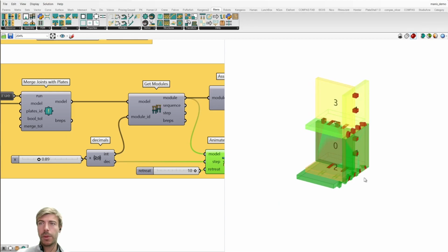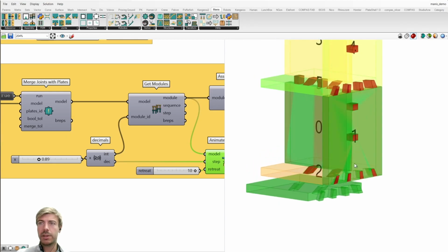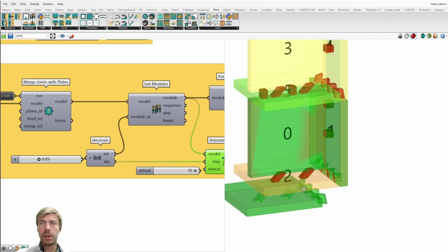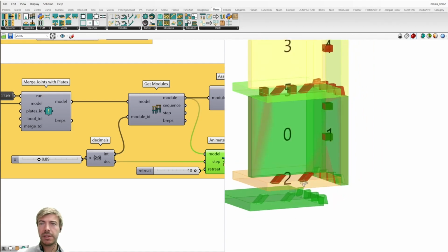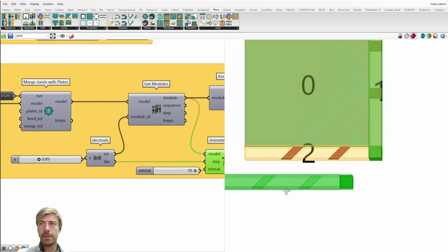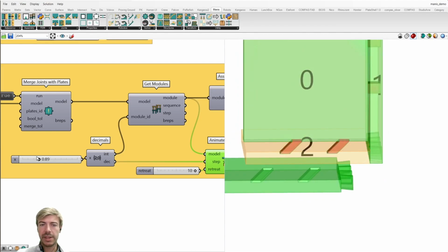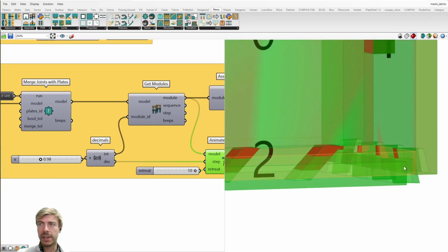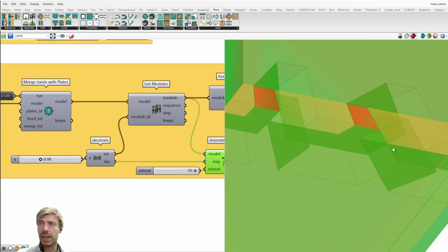And you see that both the Negiri Arigata on the edgewise connection here and the true tenon on the side-to-face connection have been influenced by this 45 degrees insertion vector. And you will see that the assembly remains compatible for both. Here you see the tenon being inserted, and also the Negiri Arigata that fits perfectly.